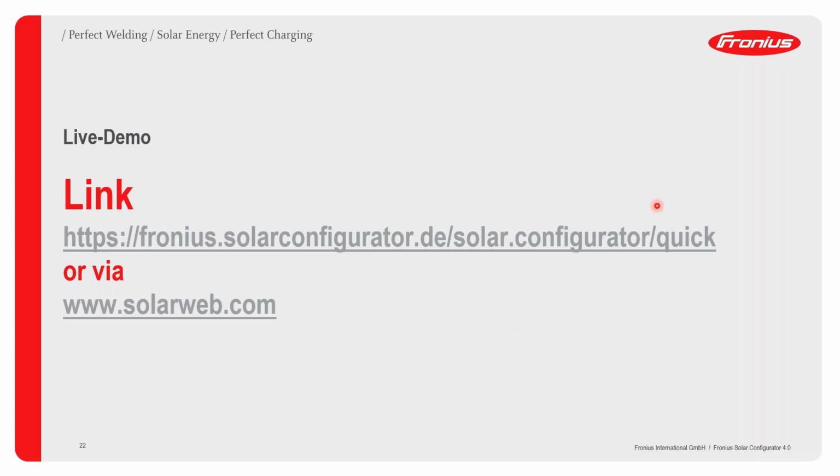Yes, I think that comes down to the short circuit current maximum capability for that specific MPPT tracker. Generally, with all Fronius inverters, if it's a 2 MPPT tracker inverter, MPPT tracker 1 will always have a greater short circuit current capacity than MPPT 2. This is why, whenever you use a solar configurator, you'll see that in the majority of cases, MPPT 1 will have a higher number of suggested modules than MPPT 2.